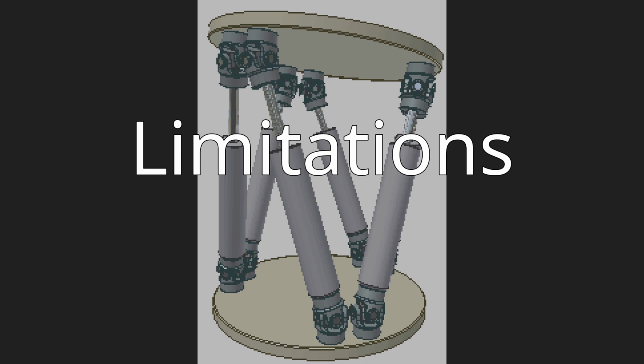While the steady cruise regime of a fighter aircraft may be able to be well simulated within these limitations, in aerial combat situations flight maneuvers are executed in a very rapid manner to physical extremes. In these scenarios, there is not time for a washout filter to react to bring the motion system back to its equilibrium, resulting in the motion system quickly hitting its range of movement limitations and effectively ceasing to accurately simulate. It is for this reason that motion and washout filter-based systems are often reserved for those that experience a limited range of flight conditions.